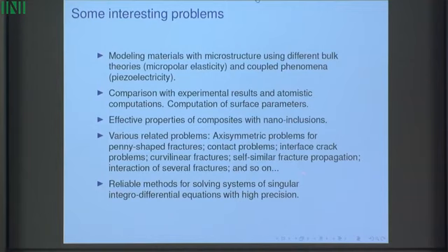Now, there are various related problems. Everything which we do for linear elasticity can be done using this theory. Should it be done? It's a different story, but maybe some interesting problems should be done. In particular, there are no axisymmetric problems for penny-shaped fractures or contact problems, so there are no solutions yet. There are no solutions actually for any shapes outside of straight or circular.